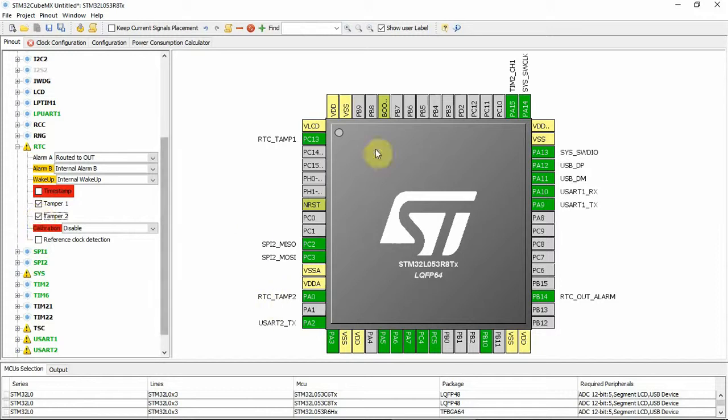As you can see, those are tamper pins. This is part of the STM32 device. When you connect those tamper pins to switches, you can put them inside your box, and when someone opens the box, you can set how the device will react. Do you want to erase the flash? Do you want to put a timestamp? And other different things that you want to do when you see that someone tampered with your product.